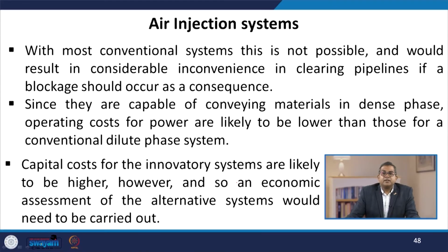With most conventional systems, this is not possible, and it would result in considerable inconvenience in cleaning pipelines if a blockage occurs as a consequence. Since they are capable of conveying materials in dense phase, operating cost for the power is likely to be lower than for a conventional dilute phase system.